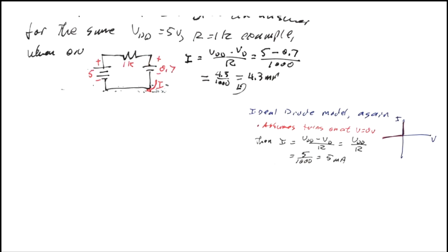But this isn't a real battery, right? This is not the kind of battery that can generate power. It can't generate any current. It just has a voltage there. So that voltage exists to allow you to solve KVL correctly, right? You can add up the voltages here and here and here and find the current knowing this resistance.